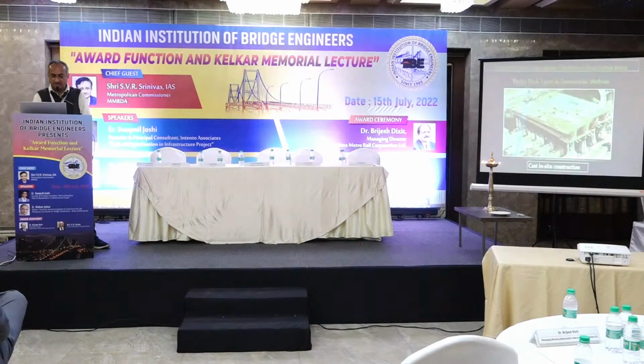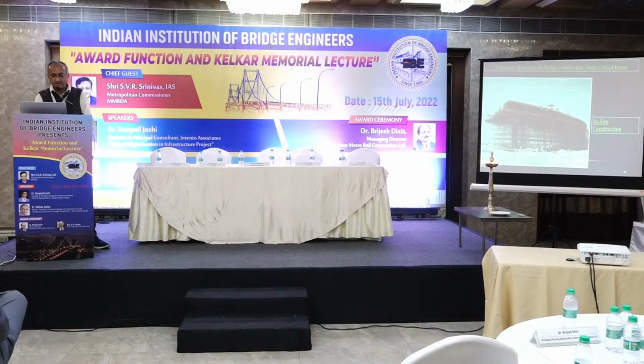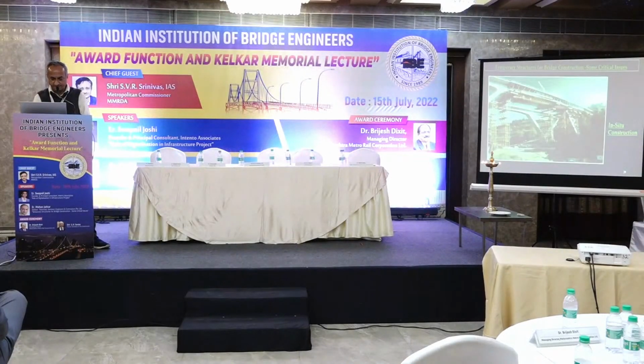Here you can see an in situ construction, typical, which everybody is familiar with, using some trestle supports from the ground. Here it's a conventional staging which is used for casting the superstructure. Here, to allow for passage of vehicles, a portal frame is formed using high capacity trestles and a truss.